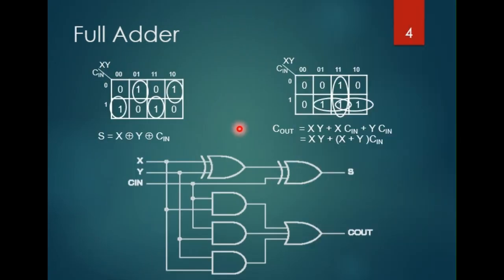To know what gates compose the one-bit full adder, you can solve the truth table using a Karnaugh map as shown here. After solving, you see that sum can be implemented using x XOR y XOR carry in, whereas carry out can be implemented using sum of products of xy, x carry in, and y carry in, as shown here as a two-level or two-stage AND-OR gates.